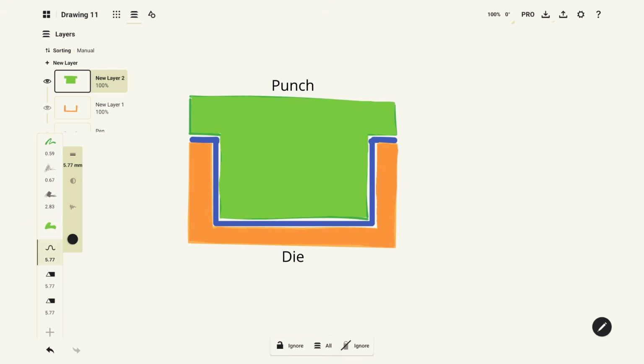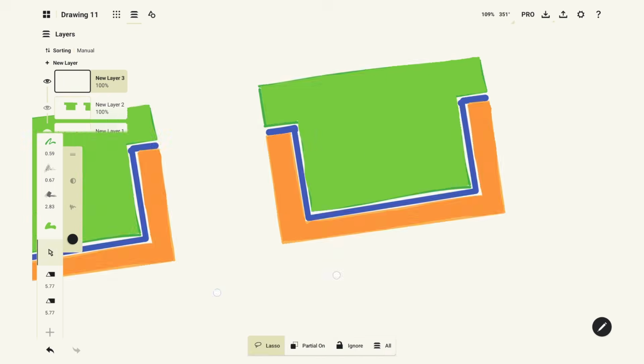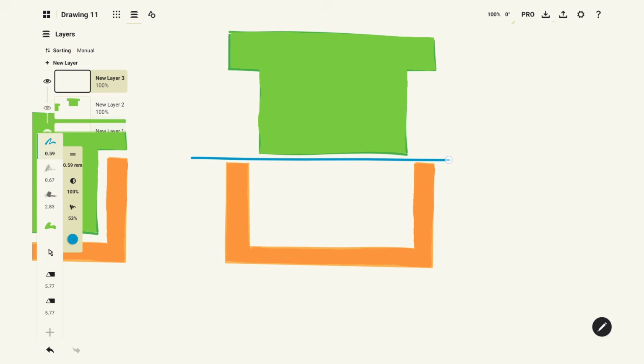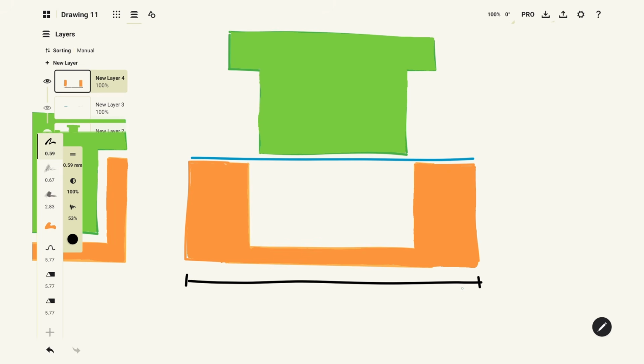But we need to understand that this is the final product after the drawing process. Initially, the sheet was just a flat circular blank, right? So first we need to place this blank sheet over the die, something like this. This means the outer diameter of the die must be at least the same as the blank size, which is 280 mm in our case.